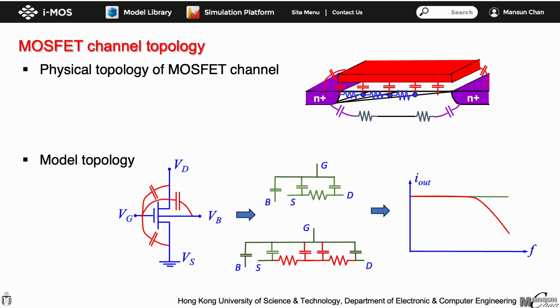When the MOSFET is broken down into two shorter transistors in series, some internal current paths colored in red will have delay to achieve equilibrium, leading to a drop in the output response. The topology becomes closer to that of the distributed network in the MOSFET channel.